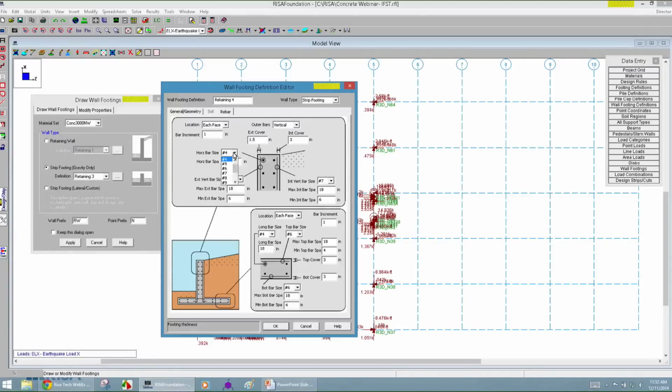So for our rebar, maybe we can set this to be number 6 bars, like on the top and the bottom, on both faces. You can switch from each face to single layer if you wanted to. The program is just going to have you tell it the cover information. I'm going to switch everything to the number 6 bars. In my practice, I've always kind of thought, hey, use the same bars unless you have a good reason not to. Otherwise, it's kind of confusing in the field about what you're doing there.